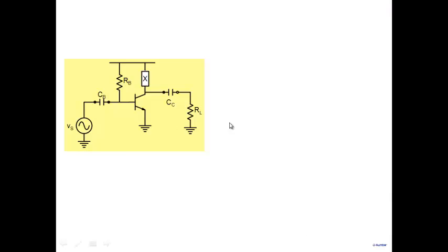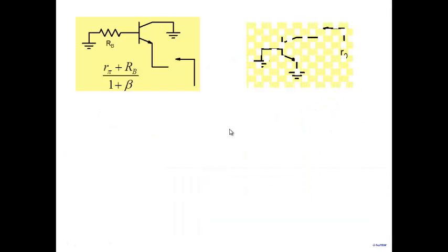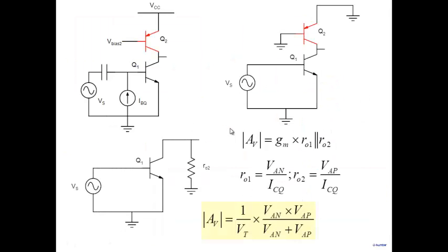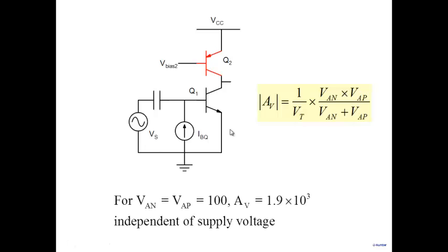So now, with that in mind, let's go back and think about what we are asking our transistor here. This is a current source, and this is also a current source. Q1 is like a current source and Q2 is also like a current source. What is the value of the current? Who decides? This bias voltage will decide the value of this current, and whatever you do here will decide the value of this current. Now, when you connect two current sources in series,